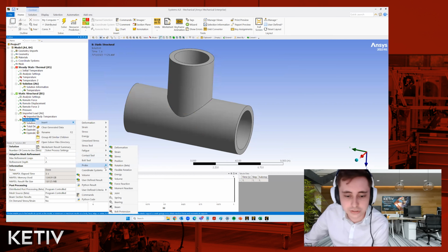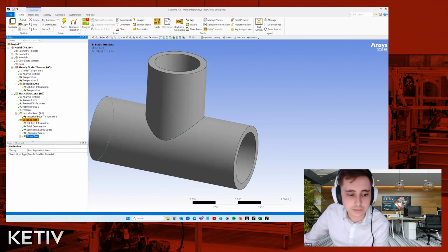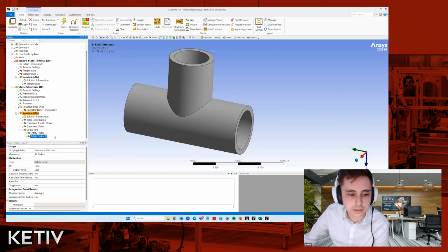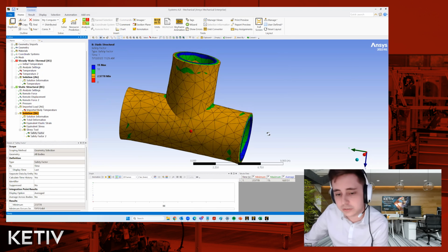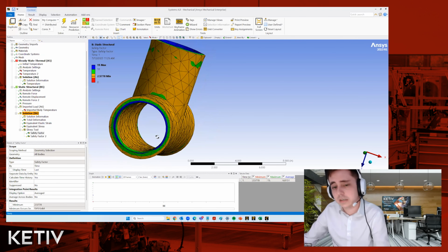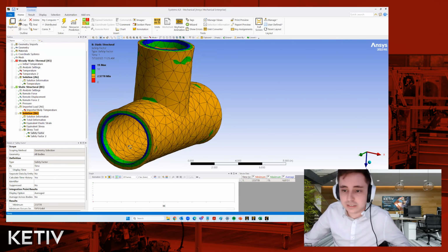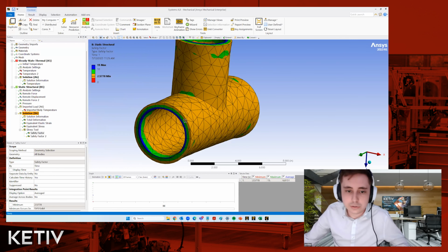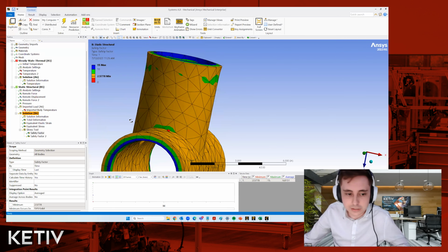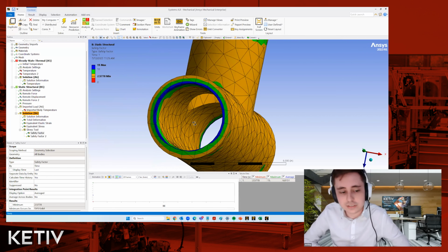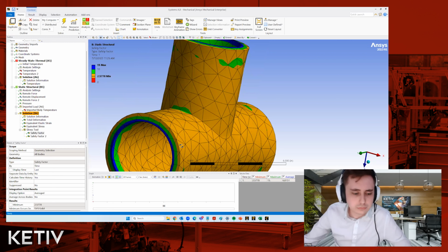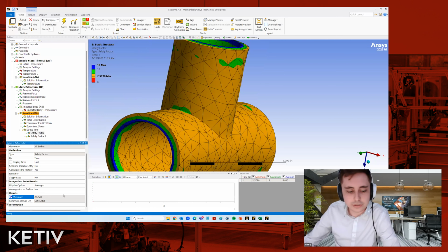We'll use this stress tool, max equivalent stress. And within our stress tool, we can insert a safety factor. And when we click on retrieve, we get this plot here. So for this particular plot, structural steel, the most expensive material that we have available, and the thickest configuration of the pipe, it is passing. So we know there's a pipe for us among these that our vendor has given us as options. But I want to report this safety factor for all of our different configurations that we have.